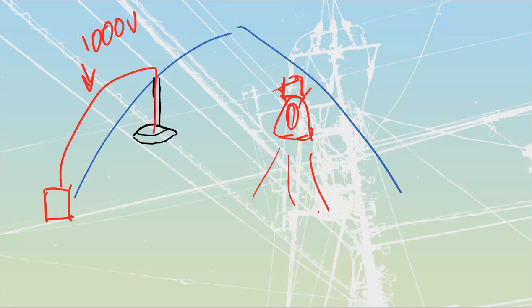The other thing that you will sometimes have is a built-in tungsten light. Tungsten halogen lights are a high temperature type of light, so they can take that environment. They're also an incandescent, so they're going to be able to switch on almost instantly. So if I place one of those inside of here, if I get a power failure, the instant that power comes back on, this tungsten light would be able to operate. And the tungsten light is tied to a little photocell that's also inside of that fixture. That photocell is just going to be watching until the main bulb restrikes. If it takes the main bulb 10 minutes to restrike, it'll keep burning this halogen, providing just enough safety lighting for people to get out of places, etc.